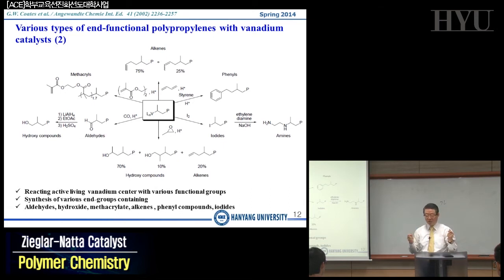So instead of the CH2 CH3 system on the surface of your final film, you form peroxide, COOH or COH, whatever, systems, and by using this corona discharge, you can print any ink systems.